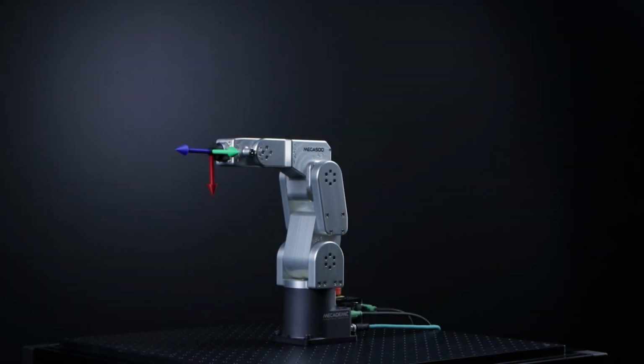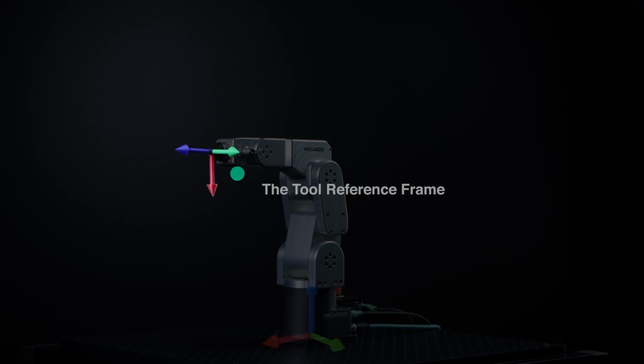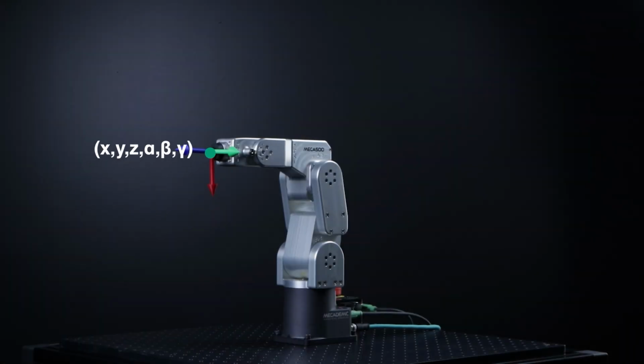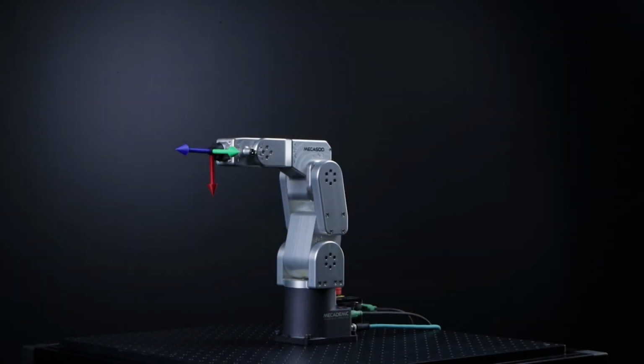In Mecademic robots, you deal with only two reference frames: the World Reference Frame, or WRF, and the Tool Reference Frame, or TRF. Every Cartesian position that the robot reports or that is specified to the robot is expressed as the position and orientation of the TRF with respect to the WRF.